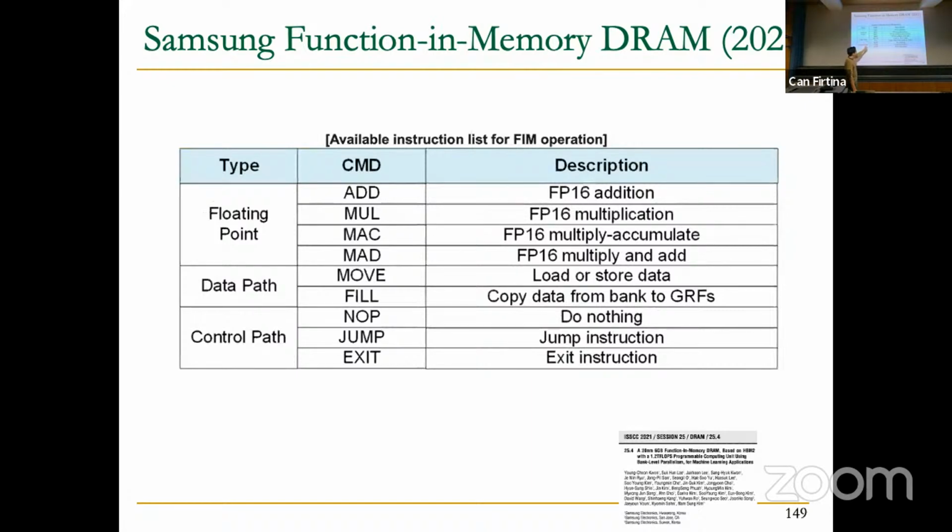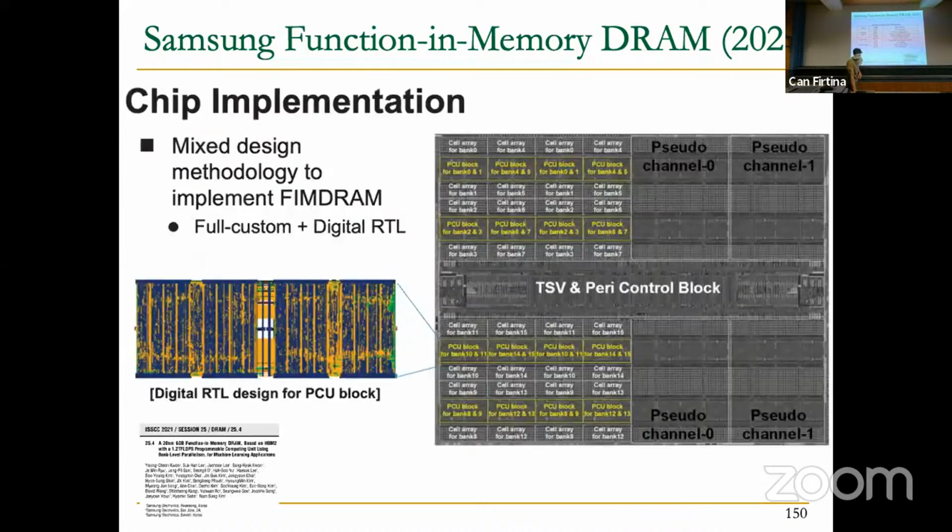For that reason, the instruction set that it has is also simpler, right? Here we have a table with the ISA: addition, multiplication, or also fused multiply-accumulate that performs a multiplication and addition basically in one cycle in terms of throughput, then some data movement instructions and some jump instructions as well to repeat, to loop over some code, etc.